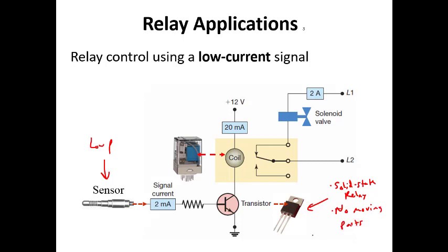Some of you may remember hard drives used to spin. They used to have a motor on them and they would spin. And when they came up with solid state hard drives, there was no moving parts, and that was a big advantage. Solid state relays have some advantages. They're faster, and they draw less. They require less power to turn them on. So there's no electromagnet. Inside a solid state relay, there's no magnet that needs to turn on.